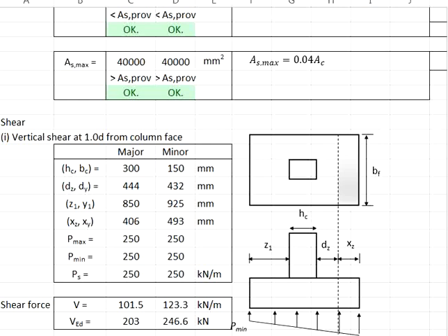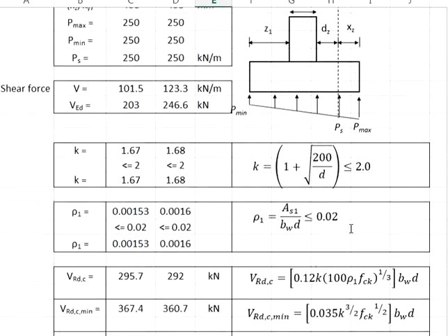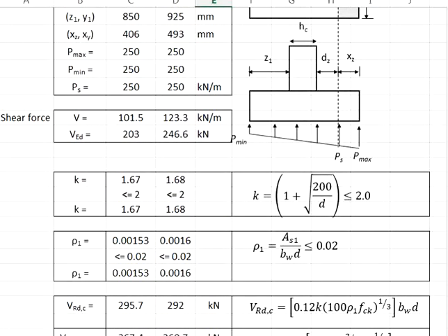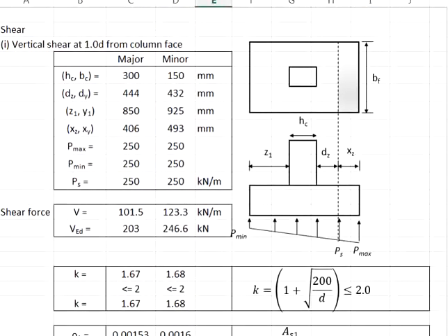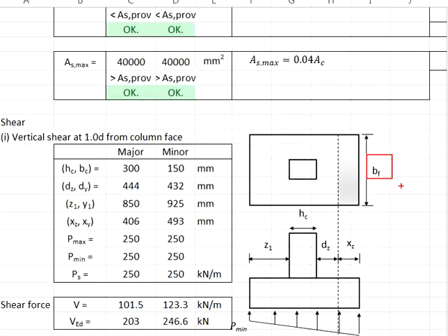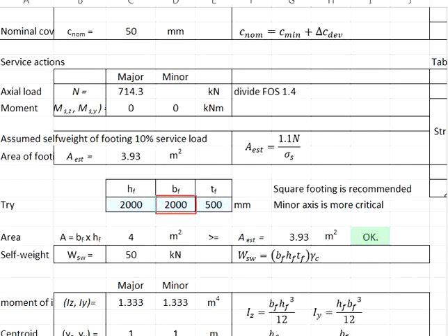Why is it so? Because these are the reinforcement bars passing through the plane, but this reinforcement bar contributes no resistance to this shear plane. Therefore, while quantifying the effective area of that particular shear plane, we are talking about this width times the effective depth, this plane. Now, how much is this width? It is equal to 2000 mm.